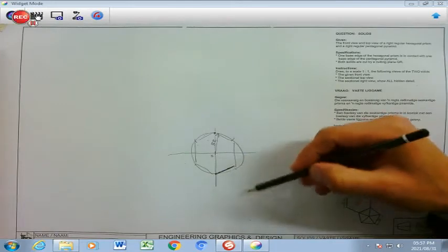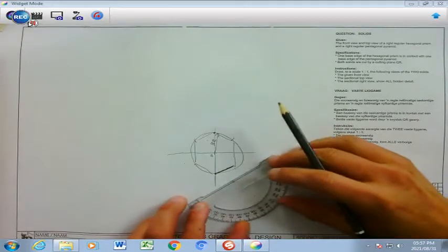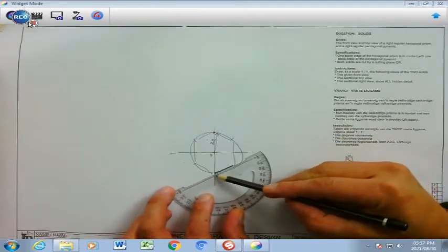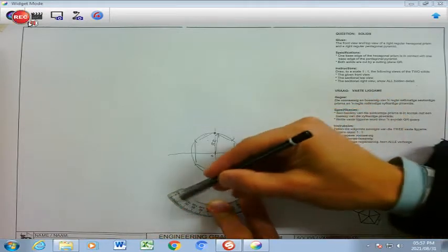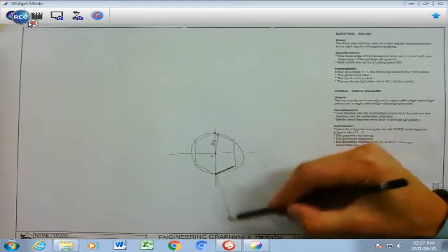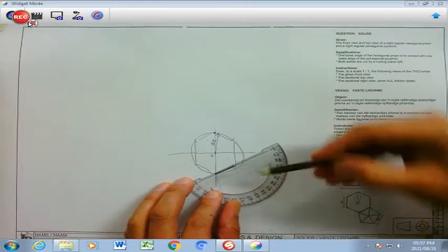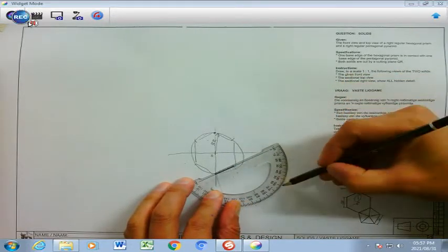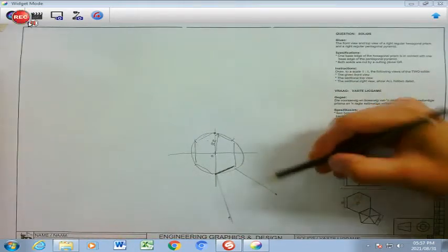This is, however, a crucial point, because that is the side that basically borders with the pentagon. So when you are going to draw the pentagon, you will need to use your protractor, and the protractor is the component that we've dealt with before. And you will use your protractor where you pin that center point to one side here, like that, and keep that in line. And you will count 72 from here, mark it off, draw the line there, move this point over so that that center point links up with the other side, count 72 from 0 here, mark it off clearly, and draw the line.